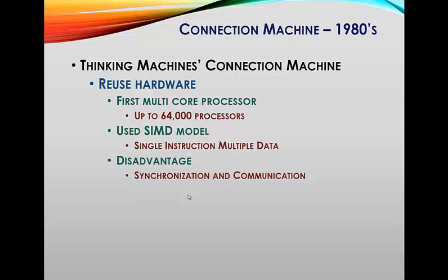If you look at the Intel i7, we have 64-bit processors. Basically, that means that they can process up to 64 bits of data and instructions at the same time. Each 8 bits combine into 1 byte. Therefore, 64 bits will be 8 bytes of processing. The SSE SIMD instruction set extends this 64-bit processing to 128-bit processing. With the SIMD instructions on each processor, you can eliminate redundant instruction memory fetches and generate 1/6 of the memory read and memory write cycles, compared to just fetching 1 byte at a time.